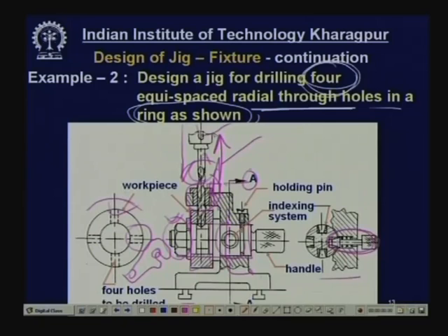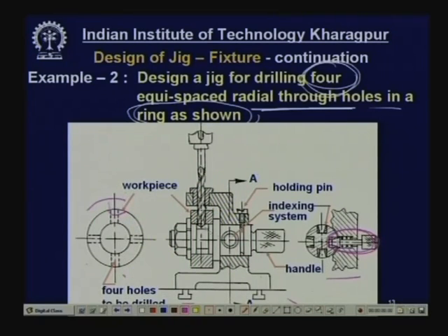inside there is a taper pin getting in. So, when the whole working is going on, this will remain in position fixed, okay, so that the job does not move relative to the mandrel and mandrel does not move relative to the part and part does not move relative to the base, all are fixed. After the completion of one hole, the pin has to be withdrawn, against the spring, and then this has to be rotated manually, approximately 90 degrees, and you release it. When you release it, this taper end will get into the next taper hole automatically, and since both of them are taper, this will be self aligned, self locating, that is this will become coaxial automatically, and then this will hold this whole mandrel in position.